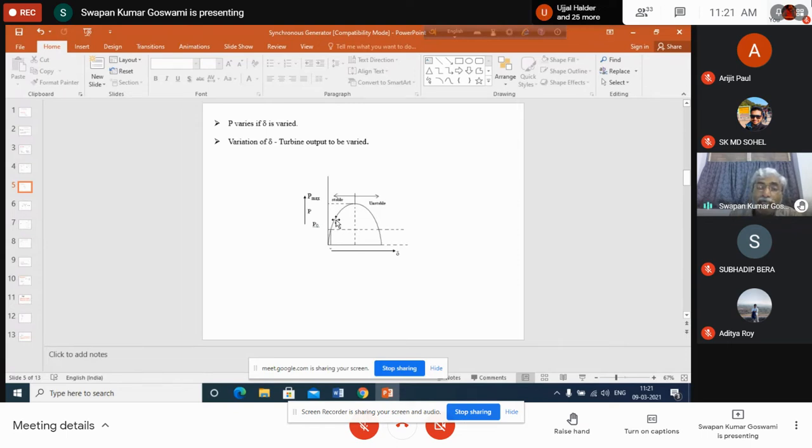Say somewhere here is the position of the new input power P0. So while delta is increasing, sometimes delta will be meeting at this point where the input power line is crossing the output power line. Okay, they will be the same, but in this process, can the generator stop at this point? Can the generator operate at steady state condition? That means at synchronous speed at this point at the first attempt.